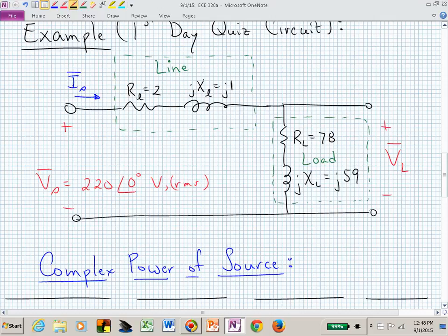They have to be consistent units in Ohm's law. If you wanted to use maximum magnitudes in your phasors, then they would both be maximum magnitudes in your V is equal to Zi expression. But in all of these power formulas, or in most of them, I like to use RMS because then we don't have to worry about this factor of 1/2 that appears. Did that answer your question?